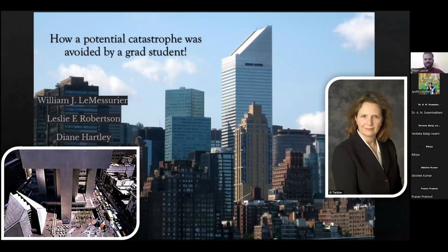But what happened was that after this call, Mr. William J. Lemessurier could not rest. He started doubting his own calculations. He went back to his design. He started checking them A to Z. And finally, he found a major flaw. It was that in all his calculations, he considered all the connections to be welded connections. But at site, due to some difficulty in doing welding, in majority of places they had opted for bolts and not welds. At that time, this was not considered as a big difference. They said bolt, weld, what difference would there be? And they went on and drilled a hole.